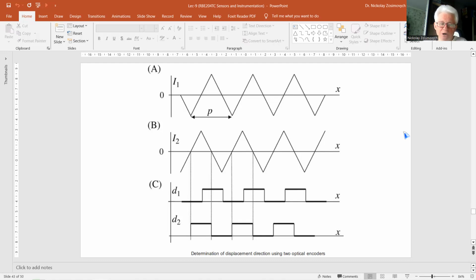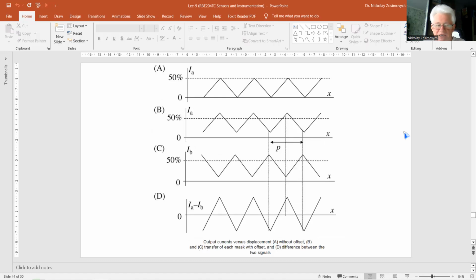And when the direction of the movement is reversed, the code is followed by 0, 1. By driving a pair of flip-flops, information about the direction is easily achieved, right? So the resolution of an incremental encoder can further be increased as follows.